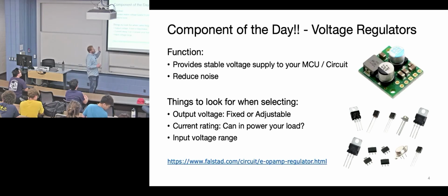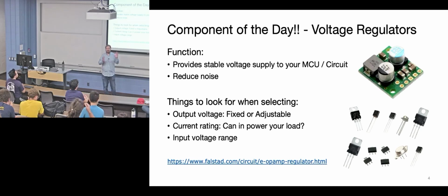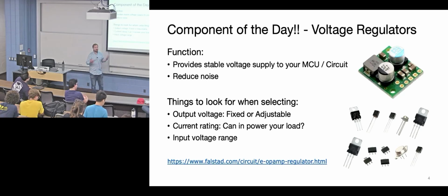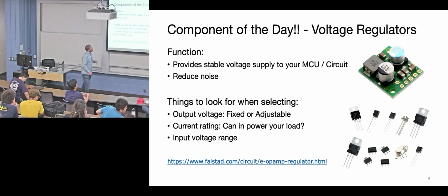And so the simplest voltage regulators are usually 3-pin devices: ground, power in, power out. All it does is take whatever voltage you put into it, within reason, and provide that voltage to your embedded system device. So when it comes to project time, if you want to make something battery powered, you need to have a voltage regulator in between.